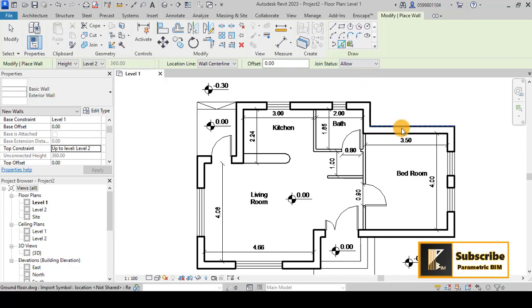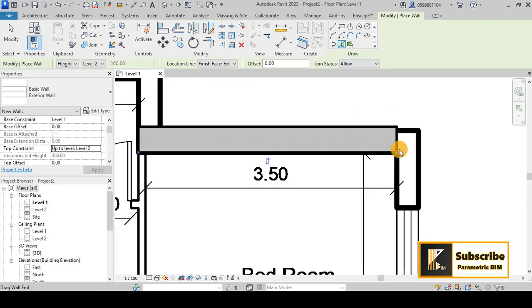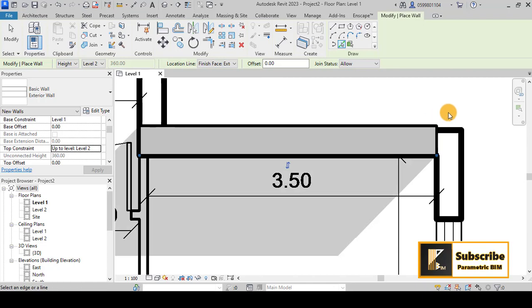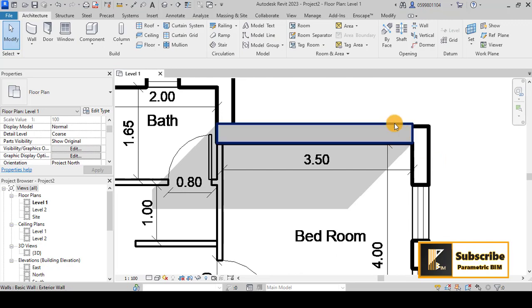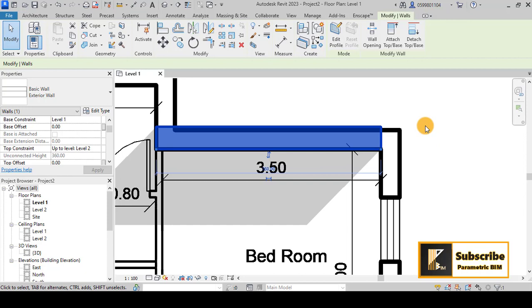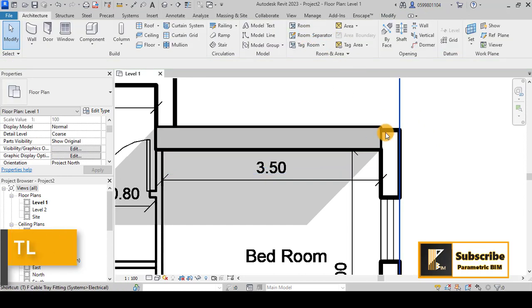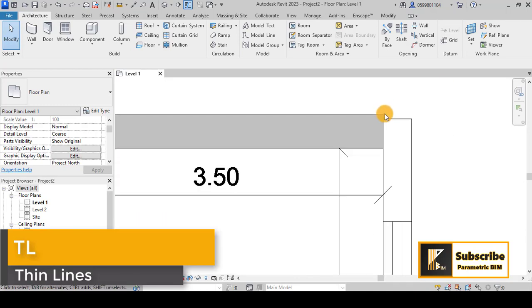Once I have that, you can see that I can pick this line. So let's try to change that from wall center line to maybe exterior. Once I click that, you can see that I override these walls by that. But let's check the thickness of these walls and then try to adjust our walls, because I see that there is something here. So maybe you can press TL to see that the thickness is more than we have.